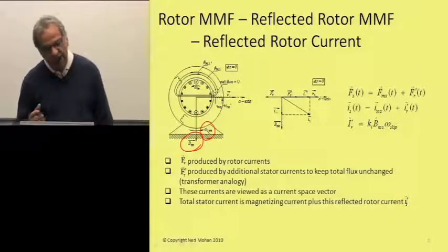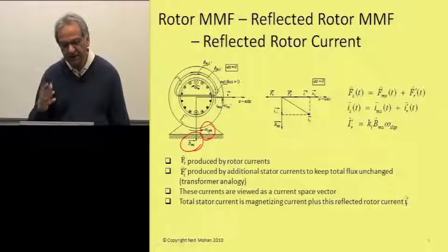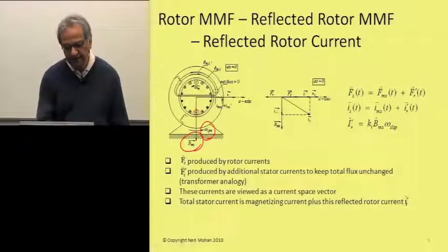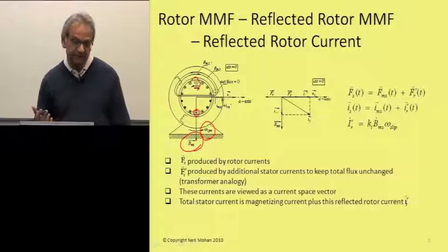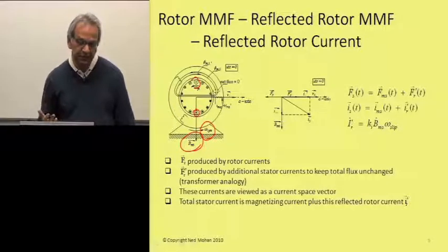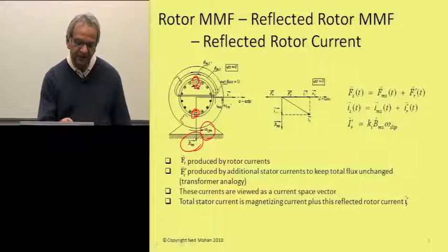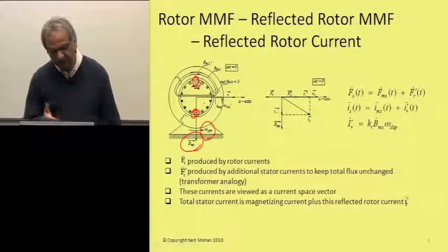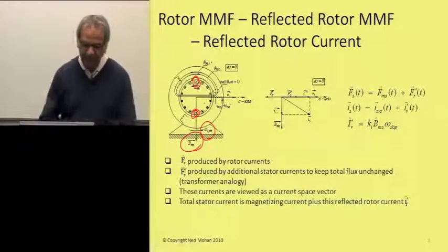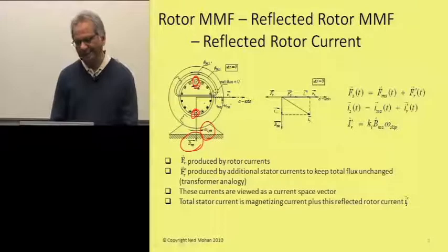In response to that, there are induced voltages in the rotor bars, which are maximum here and cosinusoidally distributed. Similarly, the bar currents are also cosinusoidally distributed, highest in these two, coming out here and going in here, and then dropping off as you move away from this axis.